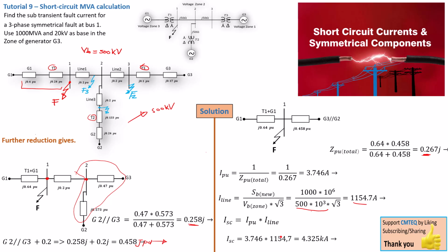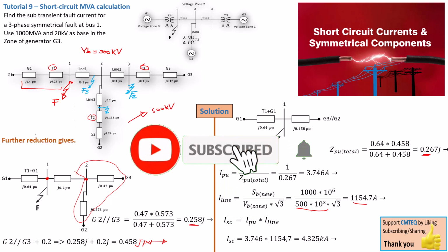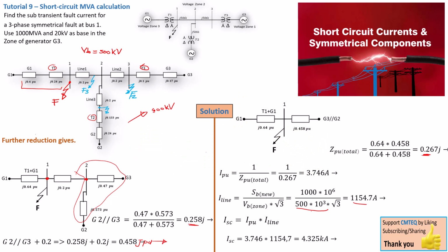So guys, this is it for this tutorial, and this is exactly how you set up and get your short circuit current calculation. Based on the level of the fault you find at this point, you will know what kind of protection you need here, so that it can break this fault without causing any fire, system interruption or a major outage.